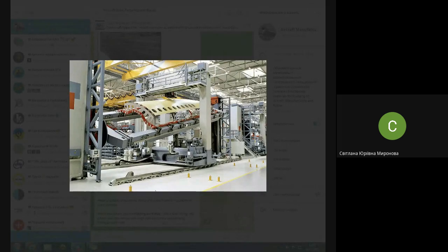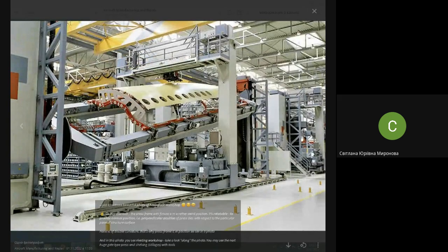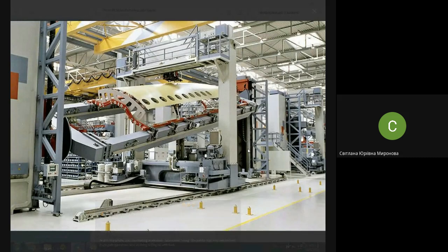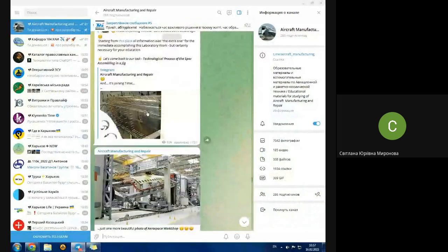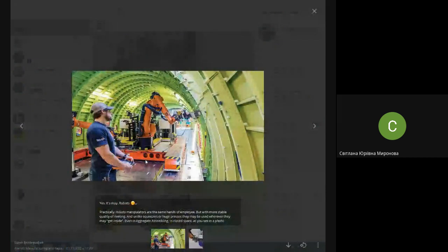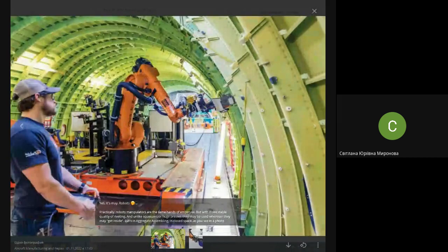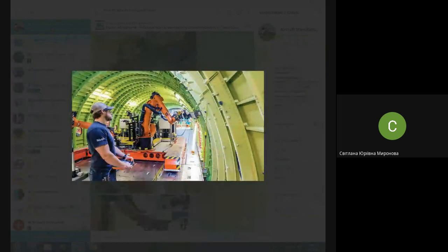What did I say before? That we have the whole shop stuffed with, pay attention, one press, next is another press, and so on, stuffed with such presses. And now maybe it's a little bit more understandable why at all we do this so-called breakdown of structure, why we assemble structure by pieces. What if we start assembling immediately in one jig? If we do everything in one working place, pay attention. In this case, if we place all the parts here immediately and start drilling them, riveting them, and so on, we are tightening it in place.